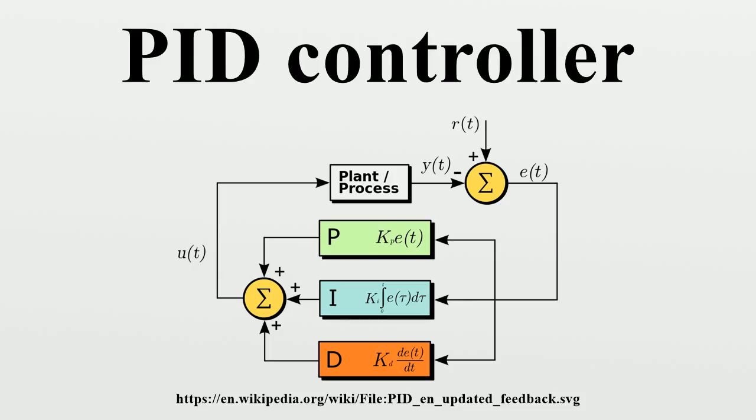By measuring the position, and subtracting it from the setpoint, the error is found, and from it the controller calculates how much electric current to supply to the motor. The obvious method is proportional control. The motor current is set in proportion to the existing error. A more complex control may include another term, derivative action. This considers the rate of change of error, supplying more or less electric current depending on how fast the error